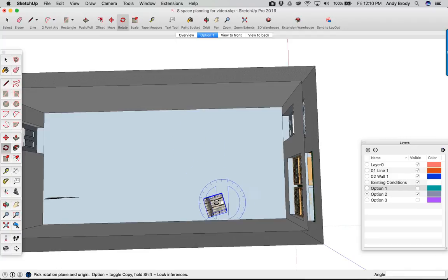When you use the rotate command, obviously I've selected the object. The rotate command, normally you'll click some base point, you click a line that is your reference line, and then you can rotate your model, your component, or whatever you've selected around. Now, the rotate command, though, works the same as the move command, whereas if you tap the Alt button, or on a PC, Control, see how there's a little plus sign next to my rotator icon? Now when I click once to make a copy, you see how it makes a second one that is rotated around from the first one. And I can type in X and 3, for example, to get several copies.